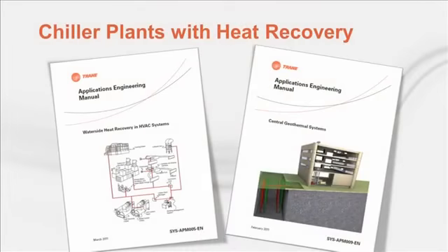With greater focus on reducing building energy use, condensing boilers, heat recovery chillers, and even geothermal can all benefit from lower hot water temperatures and larger delta Ts. Again, while today's EL focuses on the water coils, we've listed several resources related to these subjects in the bibliography.